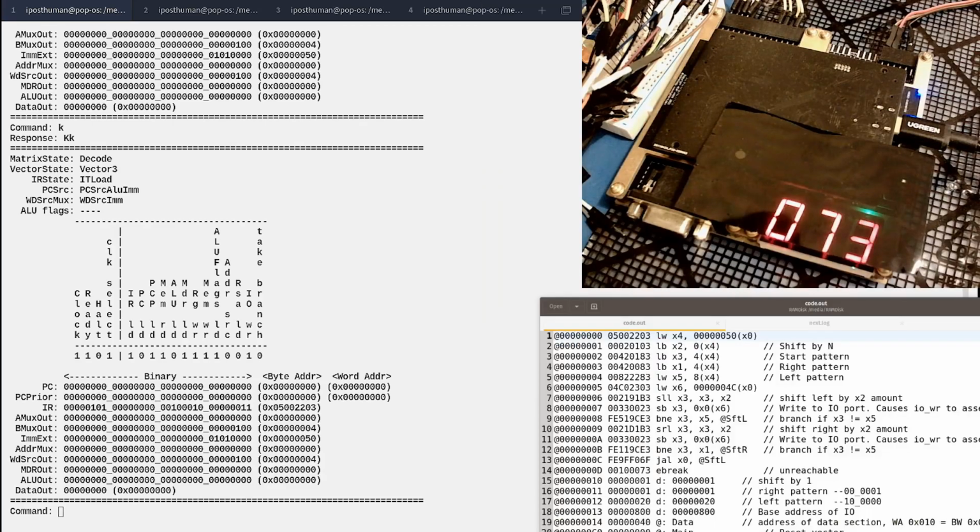And that's it. We have successfully synthesized our RISC-V processor onto an FPGA, and we have run programs via our assembler and embedded into the actual memory of the processor itself. Plus, it is actually writing to I/O, a separate register outside of the RISC-V processor. So we're well on our way to starting the next phases of the series.